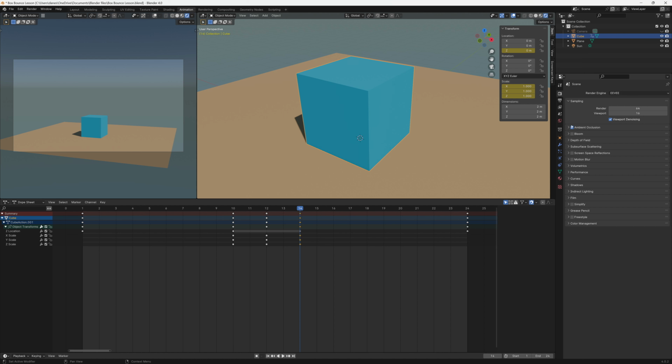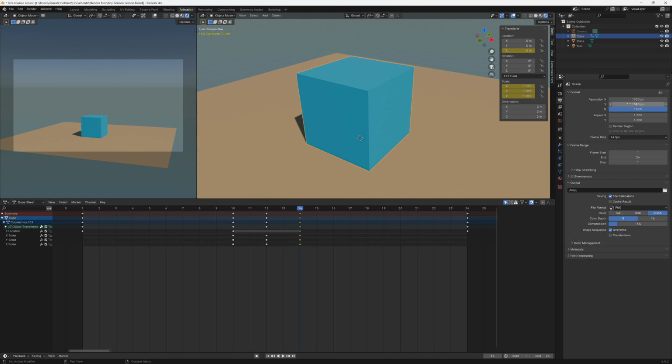We're going to turn on ambient occlusion right here just so that we get some shadowing. We don't have anything reflective. Well, maybe you want to go fancy here. Next, the default resolution is just HD, 1920 by 1080. So if you want to export this in 4K, you simply input the 4K resolution there, or you put a ×2 here. So 3840 by 2160. That will give you 4K output.